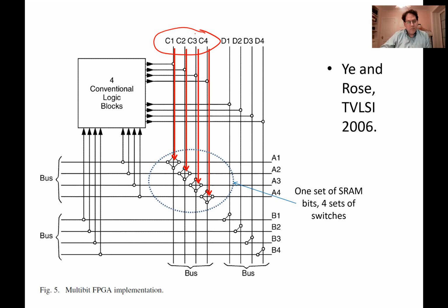So these are four routing segments that they've built inside the FPGA. And they have some signal coming in from the top here, or some 4-bit signal coming in from the top, and they want to get it into this logic. So they're going to come in from the bottom of the logic block. Let's say their routing algorithm chooses that. All four of these signals, so these are basically maybe bit 0 through bit 3 of some bus, are going to all go left at this switch block.